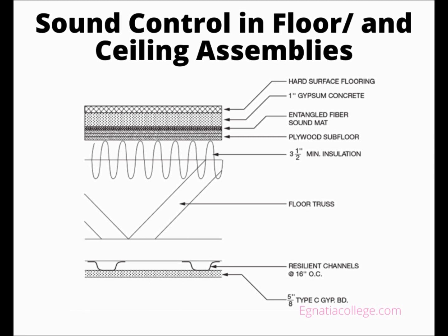Another type of sound comes into play for floor and ceiling assemblies. When a person wearing hard-soled shoes walks across a wood floor, the sound created by the impact of the footsteps can be a real annoyance to those living in the rooms below. The acoustics industry has devised a rating system for impact noise insulation. The Impact Isolation Class, IIC, is a rating of the floor and ceiling assembly's ability to isolate the sound from footfall and other impact sources. The IRC requires an IIC of 45 or more for common floor and ceiling assemblies between dwelling units.